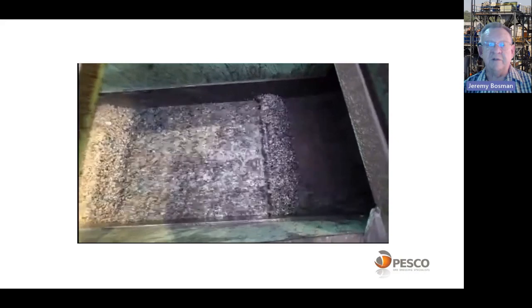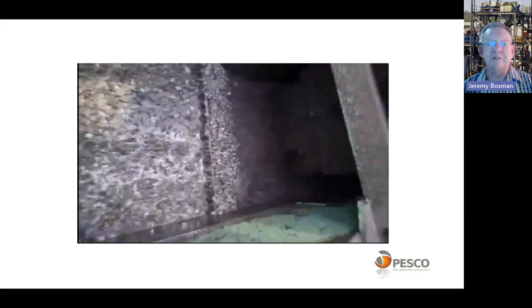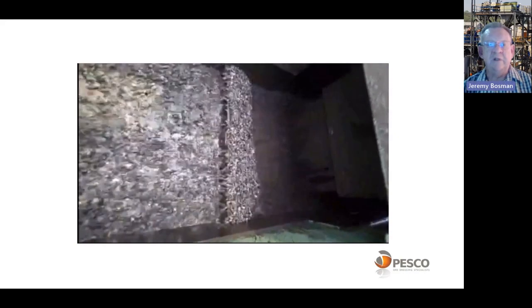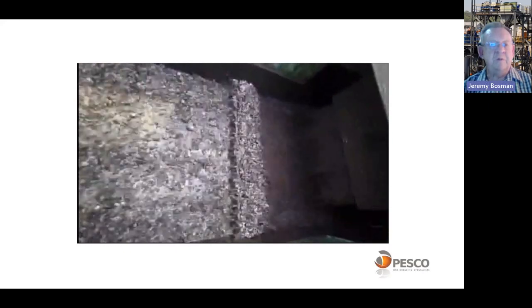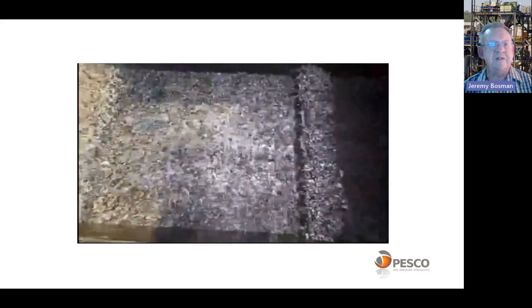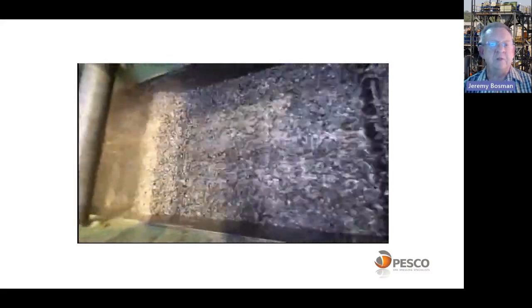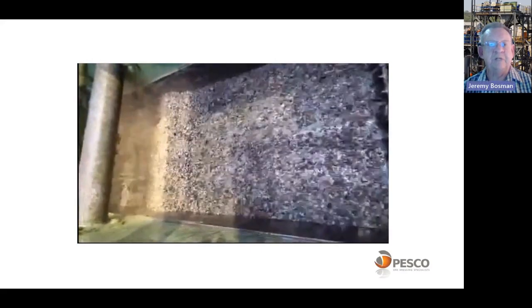And what we've got there is a drain and rinse screen which is draining. We're not overloading it. We don't have an excessive bed depth. We don't have a lot of medium carryover. We're draining all the medium on the drain section, and then the adhering medium is washed off in the sink section, like in the rinse section.